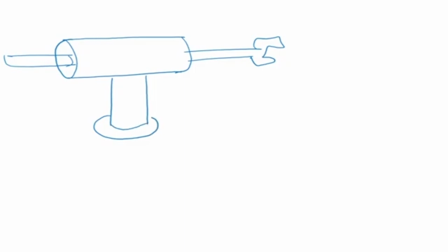When you see a robotic manipulator, first understand which are the joints, which are the degrees of freedom, and what changes when it moves. First, whether it's prismatic or revolute, and where the axis is. If you imagine, the first axis is this one, and the full body can rotate about it. That's a vertical axis, the revolute axis. The second axis is this link, which can go in and out, so this is a translating joint. So the first is a revolute joint, this is a prismatic joint. The third can rotate about the axis at the wrist, so it is revolute again. So it's revolute, prismatic, revolute.